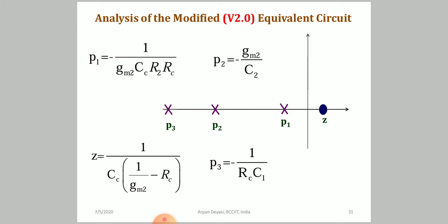Now look, of the poles, one is close to the origin, and two are away from the origin, and P3 can be easily sacrificed for the presence of Z. So now you are effectively getting 2 poles in the left half plane, which satisfies my earlier criteria that one pole should be very close to origin and the distance between the 2 poles should be very large.